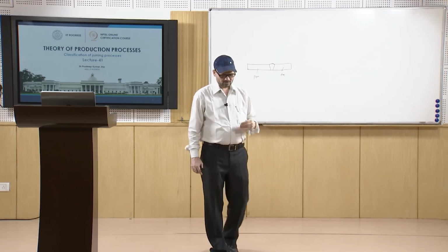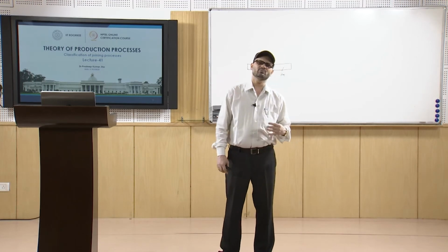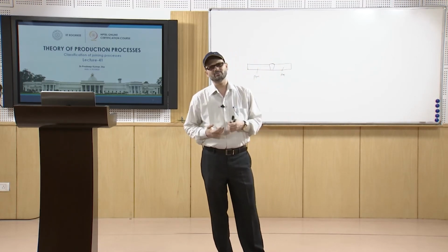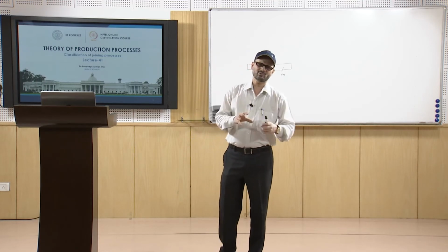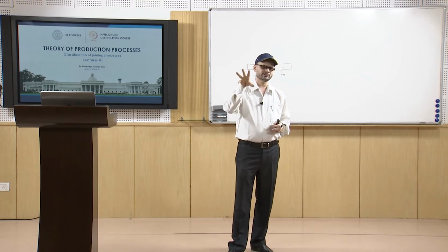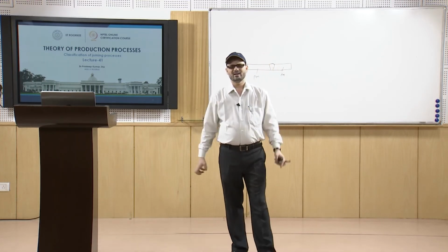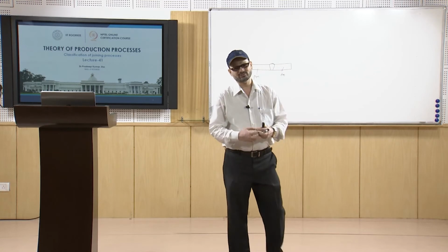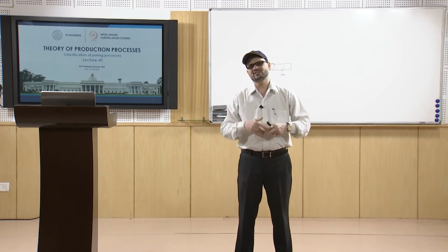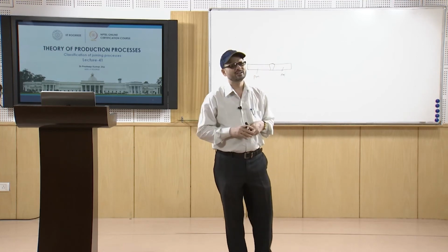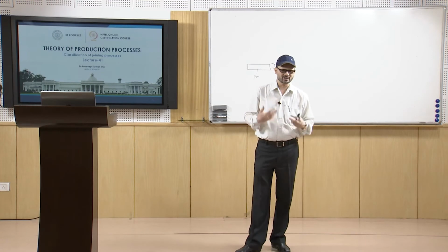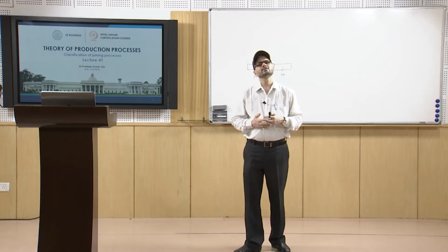Also, when we go for fusion welding, there are certainly some undesirable effects on the structure because of the large amount of heat accumulated at a point, which then moves, and the material transfers this heat through it, so some part of the material is affected. So, there will be a heat affected zone where the structure is likely to change, and it does.